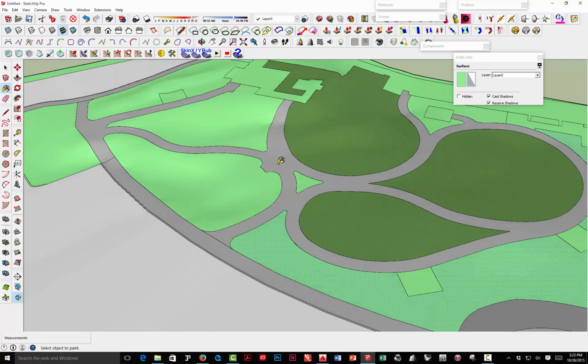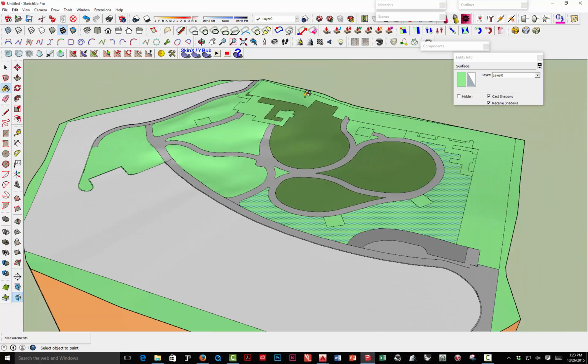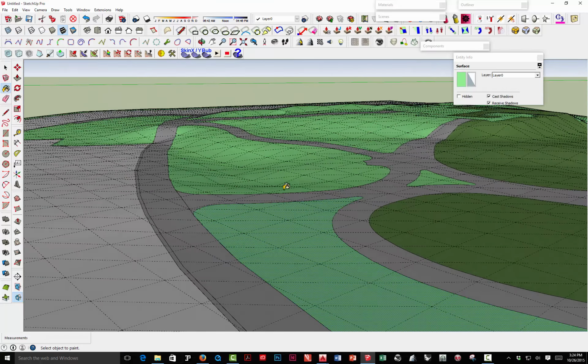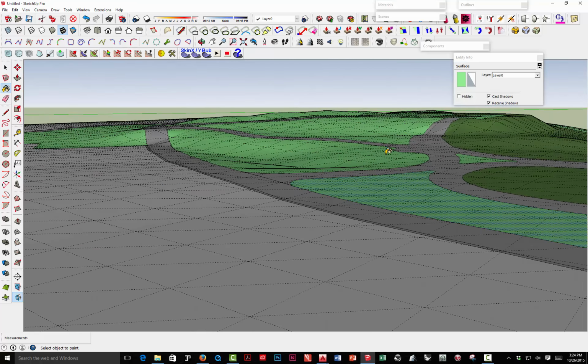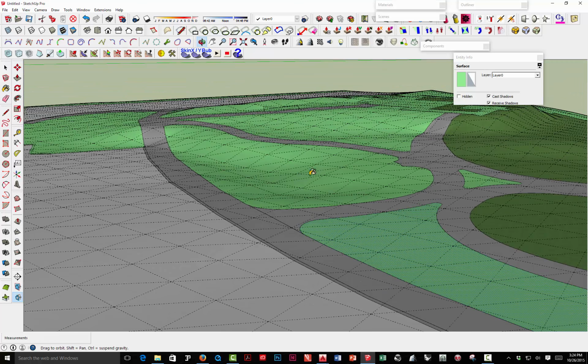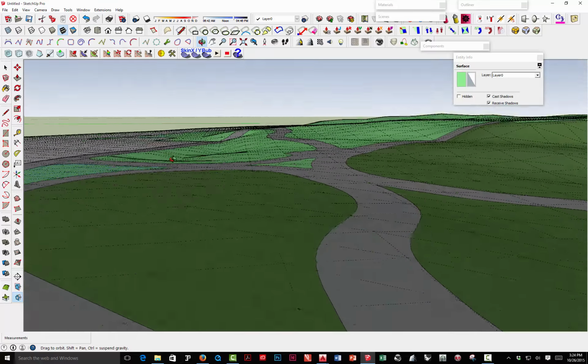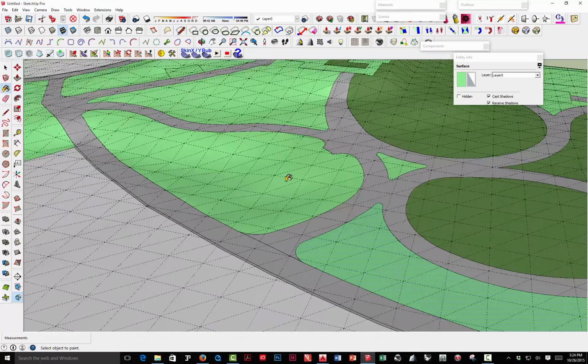And later on, we'll talk about how to manipulate the landforms. There's a couple areas like where the retaining wall is here. We're going to have to fix this a little bit in order to get the terrain to look right inside of it. And there's a little seating circle here that's supposed to be a little more level. If we look at the hidden geometry, it's averaged. You can see it forming a little bit here, like this is leveled out and then it slopes down, but it's still actually a little too sloping. I'll go over how to do that in another tutorial and in class.